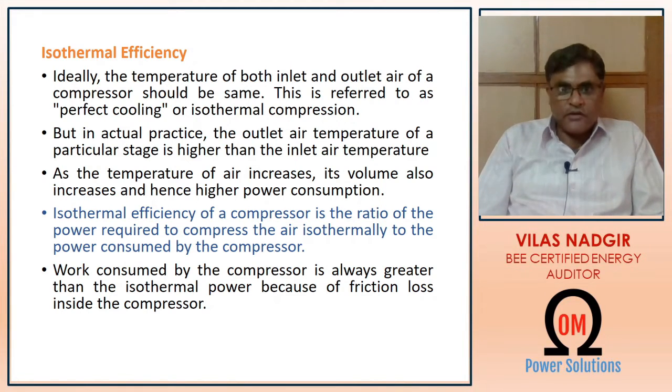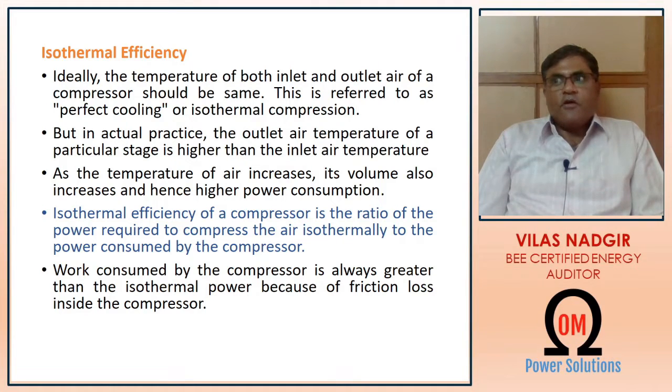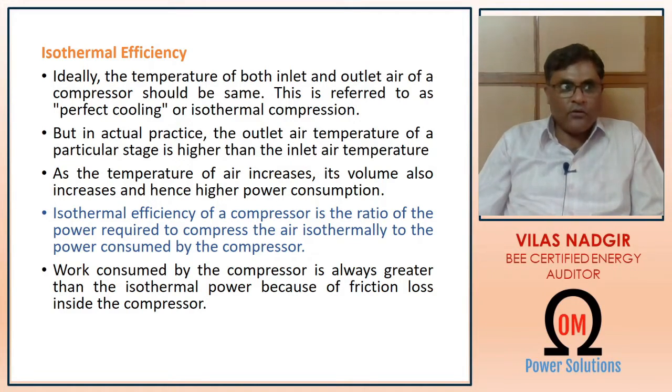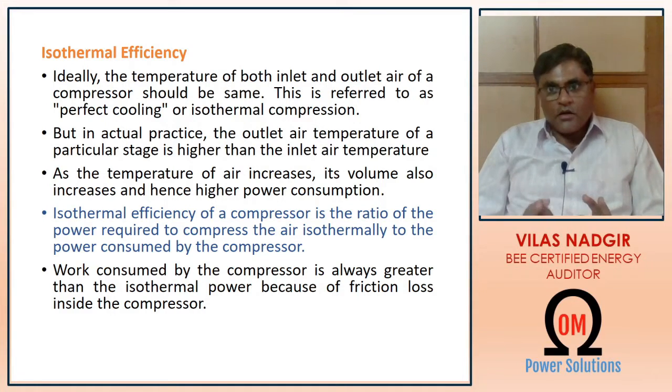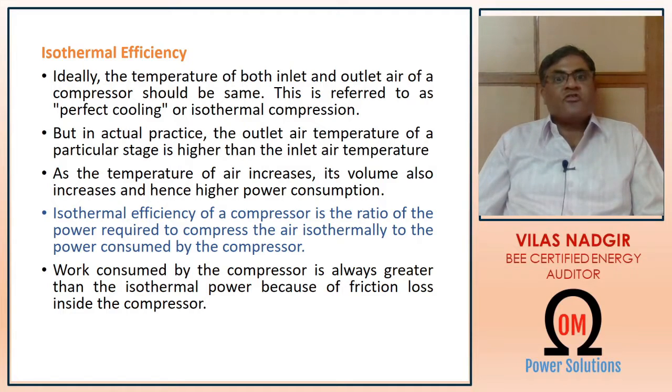Now, isothermal efficiency. To understand this term, first you need to know what isothermal compression is. Just like what we studied in the last slide, that if inlet volume equals outlet volume, then its volumetric efficiency is 100%. Here also the same thing applies. If the inlet temperature of air is equal to the outlet temperature of the air, then it is known as 100% isothermal efficient compression, or isothermal compression, or perfect cooling.